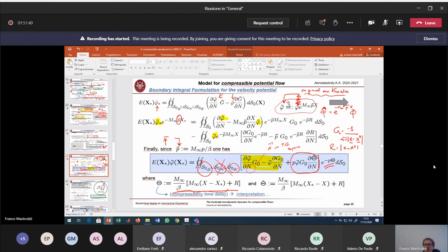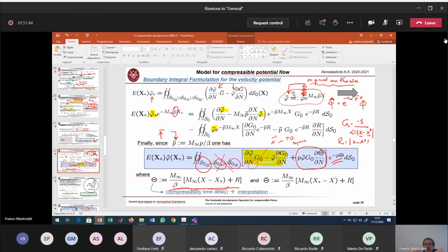But we traveled starting from the panel flutter model, the section model, the wing model, and so we considered all the background from the structural dynamics, and we built all the background for the unsteady, incompressible, and also compressible linearized potential aerodynamic.